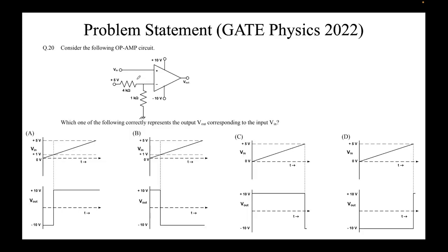Okay, I'll move forward and we'll solve the simplest problem that you can get with an operational amplifier. Whenever you're solving problems, you must identify a few things first. You must check whether the feedback network is there or not. First check, always: feedback network present or not. Second, if it is present, then is it positive or negative?